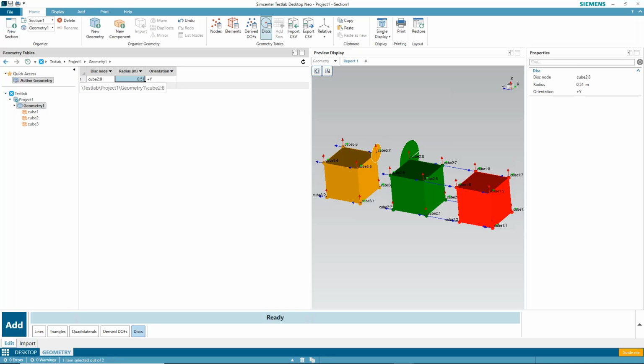Okay, so then if you had a torsional displacement, velocity, or acceleration, I could animate that, and then you would see these disks shift. So perhaps if you had like a shaft, and you wanted to see twisting along that shaft, you could have a torsional transducer on either end of that shaft, and then we could see it animate and shift, and you would see these radius lines move based on the torsional velocities.